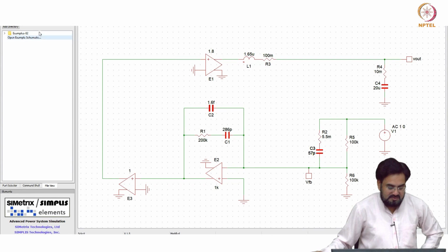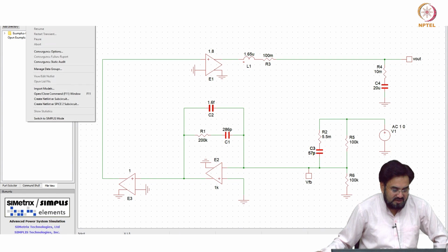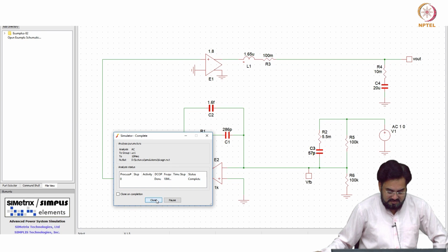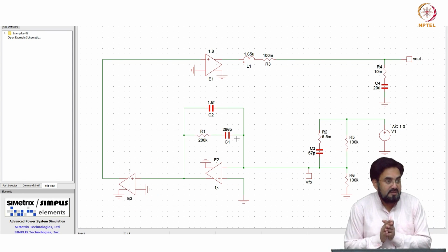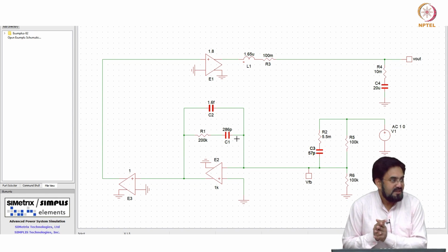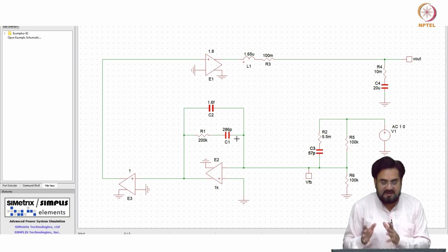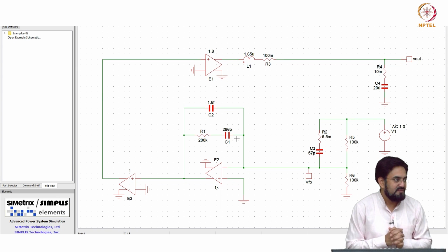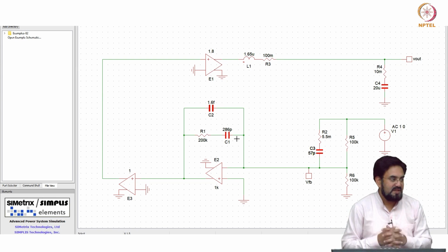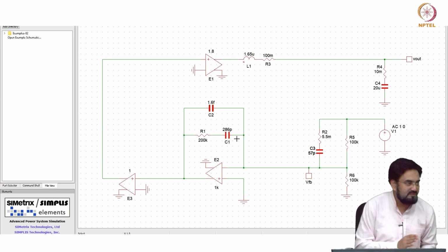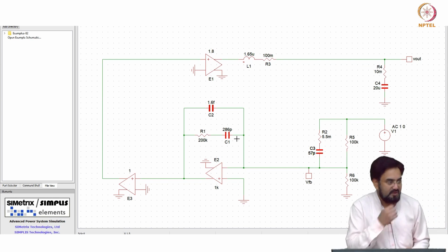So one thing you need to remember, these poles should not affect your loop gain, which is why we are keeping them outside UGB. They may have some effect on your phase margin, because even if you keep them 5 times away, the tan inverse of that pole divided by omega UGB gives some contribution, maybe 5 degrees or 10 degrees.